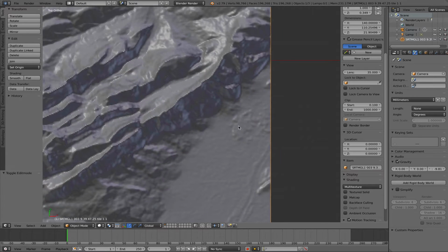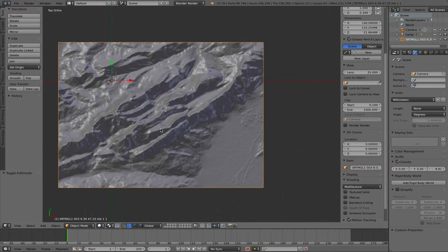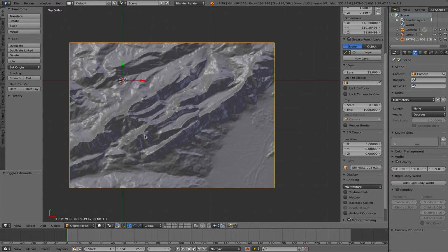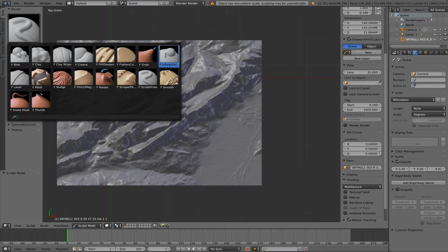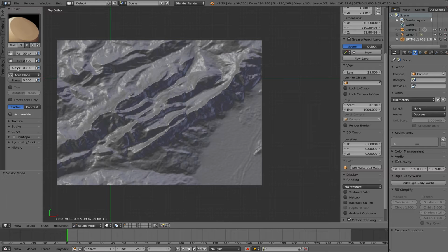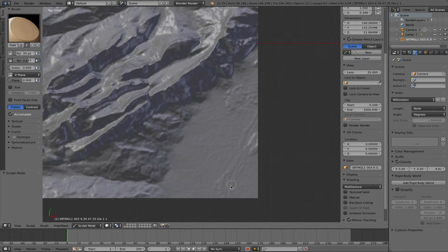I want to flatten this area. I don't want this in my final object. This can also be done in Meshmixer, but I really want to do this in Blender. Blender also has a sculpt mode, and in this particular sculpt mode there's a flatten brush that I'm going to use, and I make that a little bit stronger, and I limit this to the Z-plane. So with that, I can actually flatten out this area here, just brush over it.